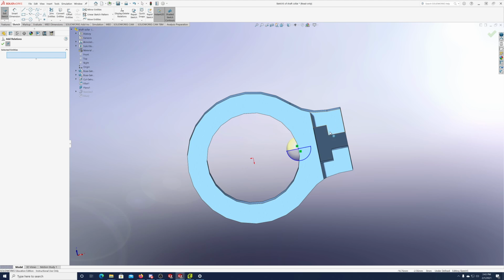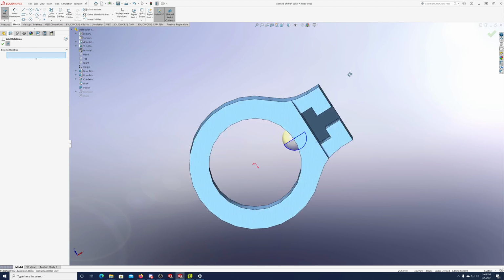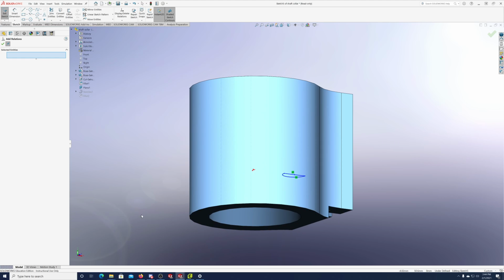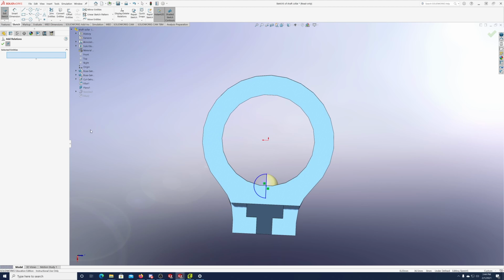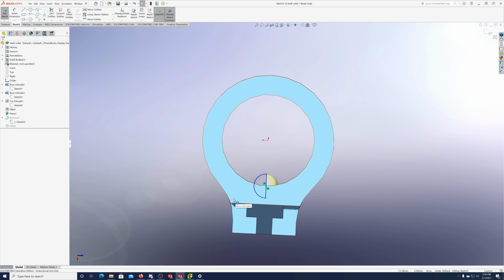I've got it sideways, but it's oriented funny, so when I drag it, it goes the opposite way. So what if we add a relation? I'm just gonna try and get it fully defined here real quick and just see what happens. I might have the same problem you did, but if I make that horizontal there, okay, that didn't really help get it defined.